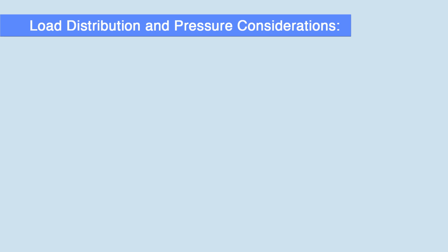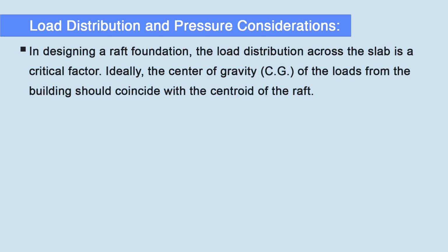Then the next is load distribution and pressure considerations. In designing a raft foundation, the load distribution across the slab is a crucial factor. Ideally, the center of gravity of the loads from the building should coincide with the centroid of the raft.